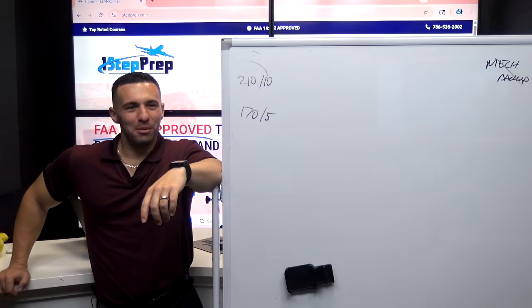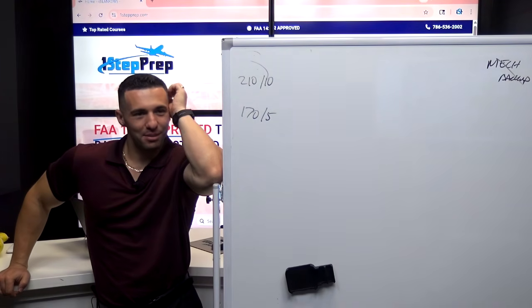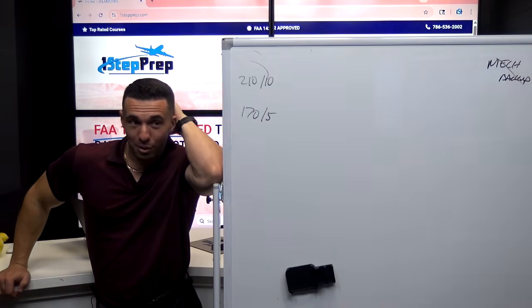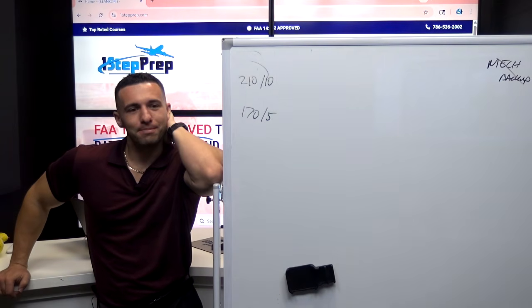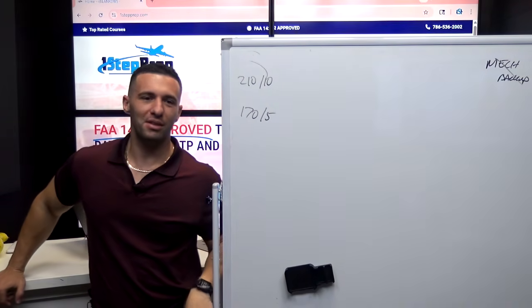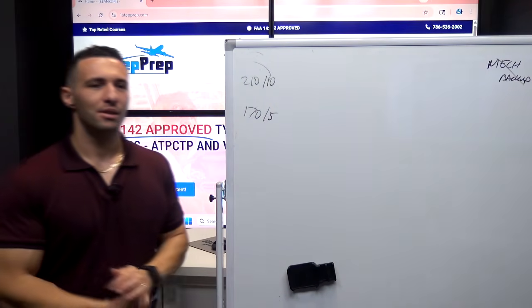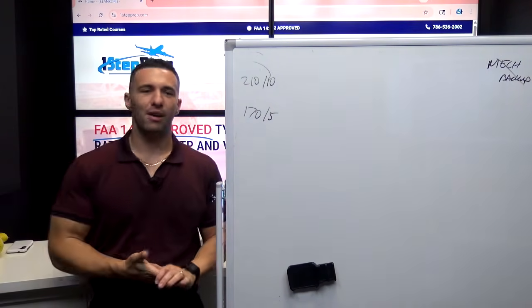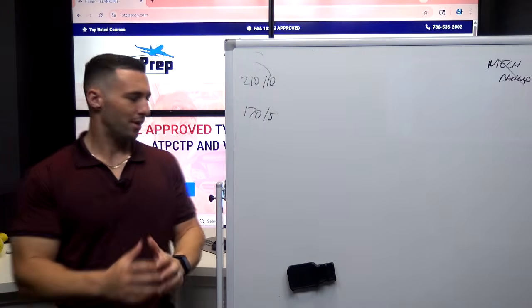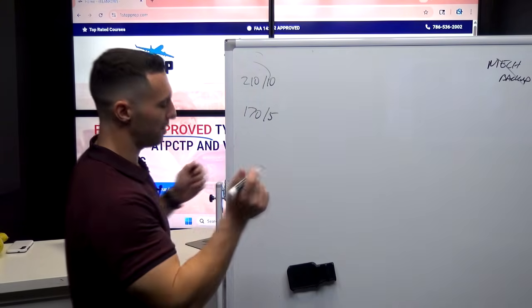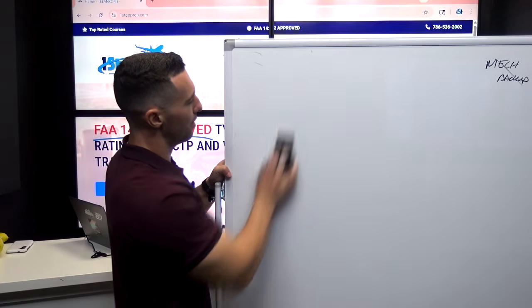Please explain again the difference between VLS on the MCDU and the one on the speed tape. Yeah, man. So the VLS on the MCDU is basically a fixed number. The FMGC calculates and populates a number, right? So let's say it's 135. I'm just going to throw out some example number.